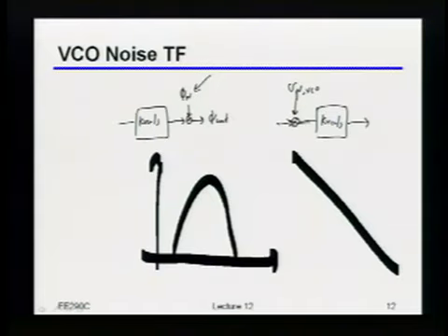That's true. Although if I wanted the same range and I had half of the KVCO I used to, I would have to double the loop filter voltage range, and that may double the voltage there, but you're right. So maybe, if it makes it easier for you to think about, imagine that I just halved the charge pump current. Then I think everything would do exactly what I'm saying here. Other questions on this?